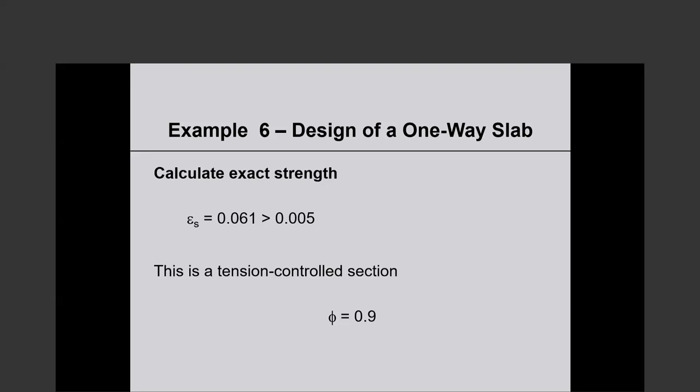That the concrete strength switches you from under reinforced to over reinforced. Yeah, I think you're talking in old terms, 3/4 of rho balanced. Your under reinforced is up to 3/4 of rho balanced, and you went just a little bit beyond. I think that's what you are saying.